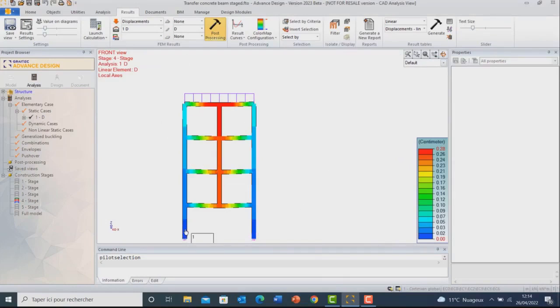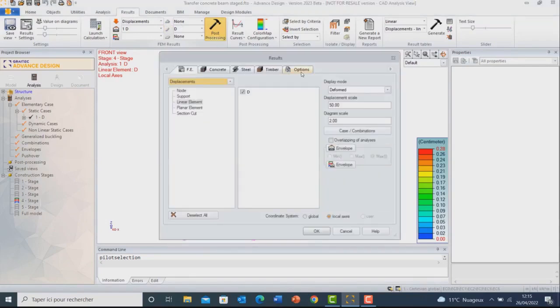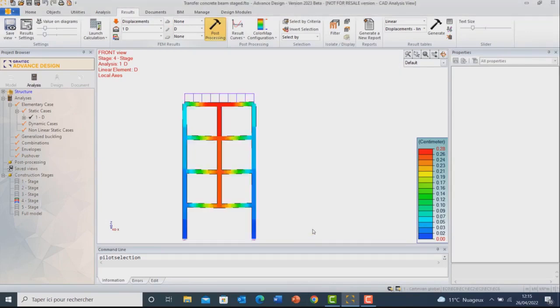So we're currently seeing the results of this structure being applied, having these loads only, without taking into consideration what happened before, if we wish to do so. So we will get back to the cumulative results. Also, the user has the option to see the envelope. So the envelope for the cumulative results, let's say for this stage and the previous stages, by clicking this button over here, we can see the envelope of results from this stage and the stages preceding it.